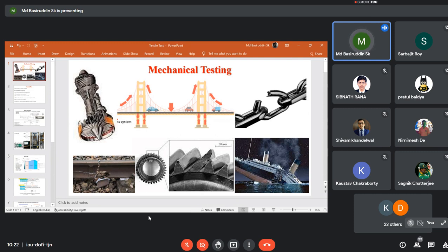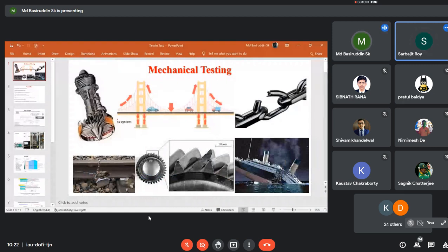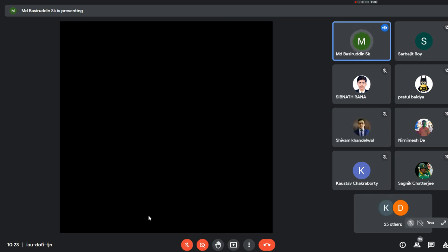Now, someone said creep. So why creep? It is subjected to high temperature, and of course, during rotating, some load is experienced by this blade. So at high temperature, loading conditions are there, right? That is why we can say that in certain cases the failure may be due to fatigue as well as creep. So from this figure you can say that a particular loading condition alone is not responsible for failure of parts or components. Rather, it is a combination of different loading conditions, right?